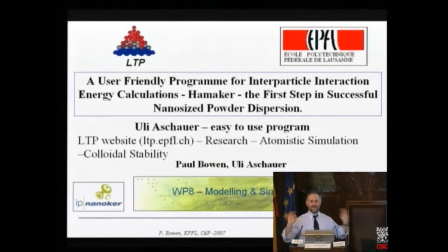I think I've convinced you, and I hope that you're convinced. If you have aggregated powders, you have to admit it and you have to solve the problem. Otherwise, you're wasting time sintering and characterizing. I've seen too much of this over the past 10 years. It's such a shame. Have a little bit of patience. Stay with the first steps. You sometimes need 6 months to work out how to disperse and characterize properly at stage 1. The rest is much easier afterwards.